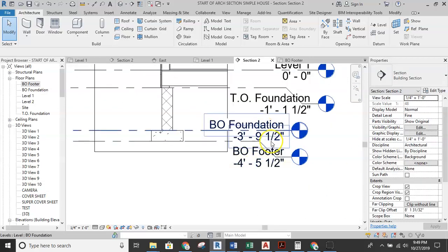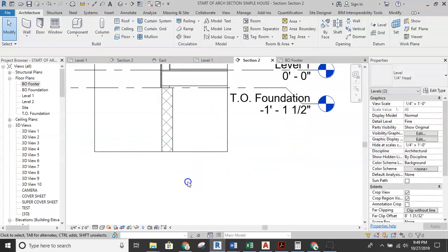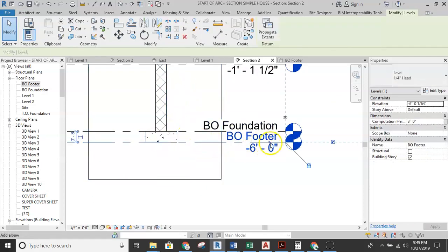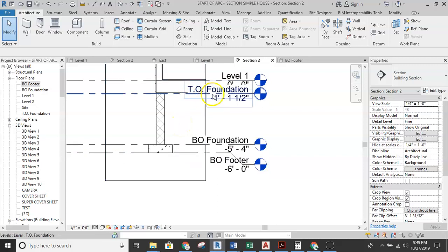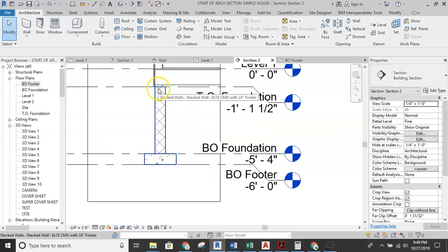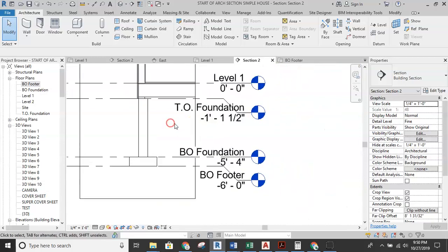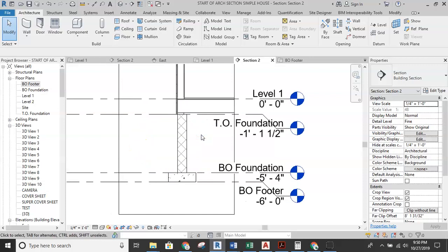And if we wanted to change this up and actually make these change in height and pull this down, make our section come down here with us, so we can see this all pulls and it's nice and clean, keeping everything together the way it should be. So this method seems to work out great, and hopefully aids in drawing different types of walls, and really should be useful when we get into doing garages where we have to do a 6-inch cap and the like, basically 3 different walls together. So hopefully you're able to follow through with this and master this stack wall system for foundations.